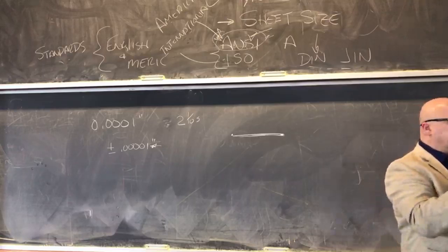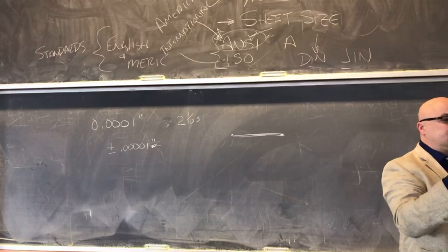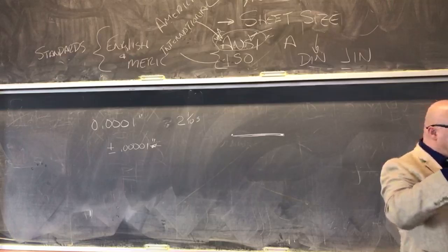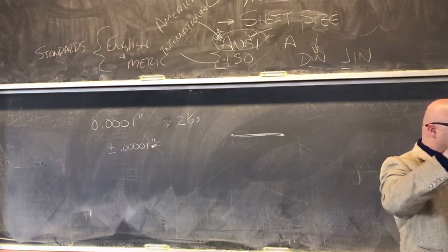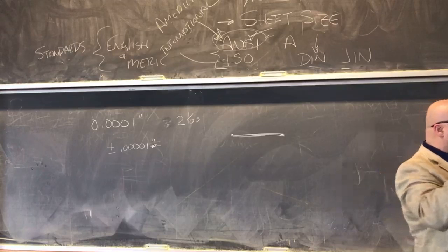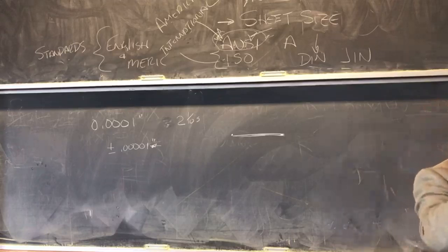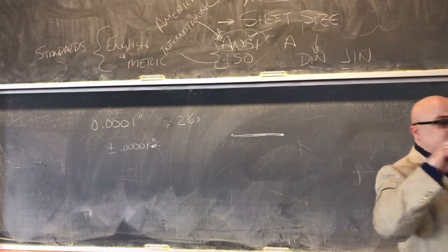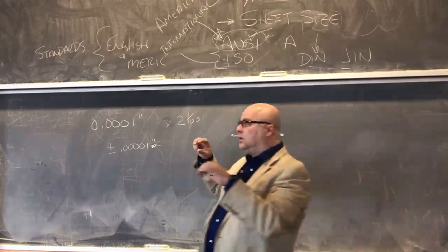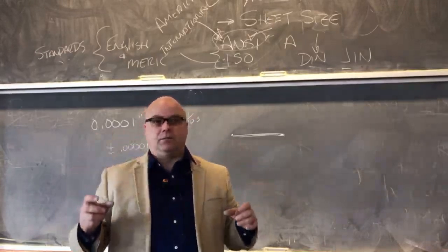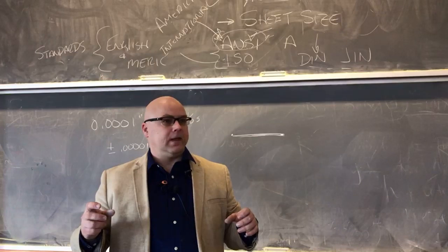Well, you need to know the variation of the shafts. So if you're purchasing the shaft, say the shaft is a pin of some kind that you're purchasing, you need to know how much those vary. Because if the thing has to fit through the hole, then you certainly need the hole to be bigger than the largest size that shaft is going to be. That makes sense? Now, what else do you have to know? Anything?